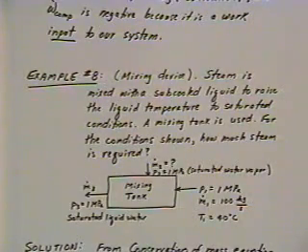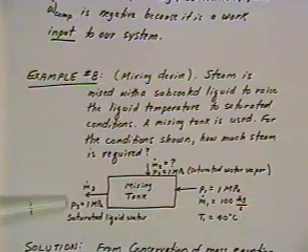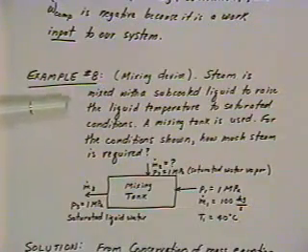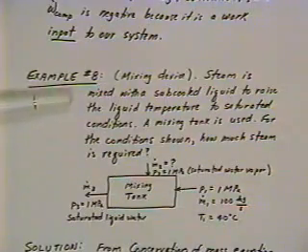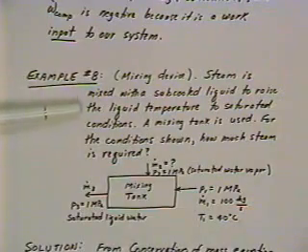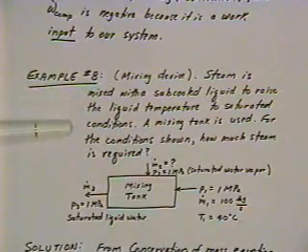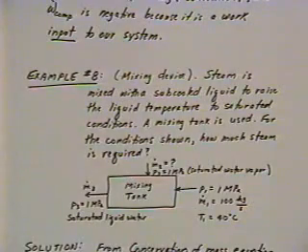And so in this particular case, we've got a mixing tank set up with 2 inlets. We've got steam coming in one side. We've got subcooled liquid water coming in at another port, and leaving we've got saturated liquid leaving. And so what this is we've got steam that's mixed with a liquid. In this case it's going to be subcooled liquid, and we'll remind you what the definition of subcooling is in a minute. The whole point of this is to raise the liquid temperature leaving to saturated conditions. In a power plant, for instance, you have a higher efficiency in the boiler, for instance, if the water entering the boiler is at a higher temperature.